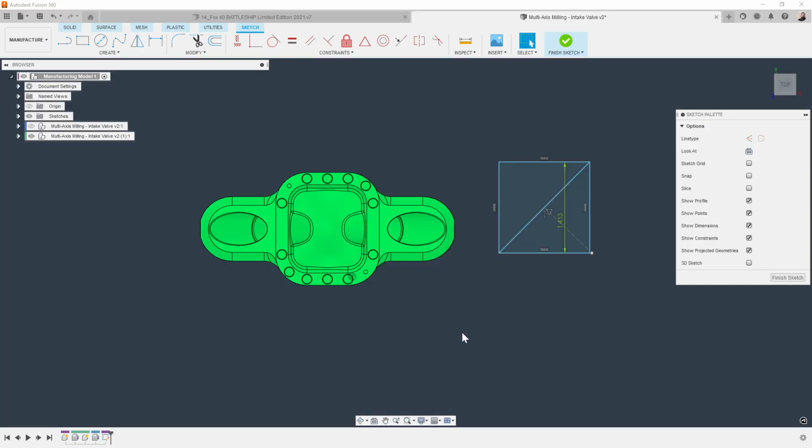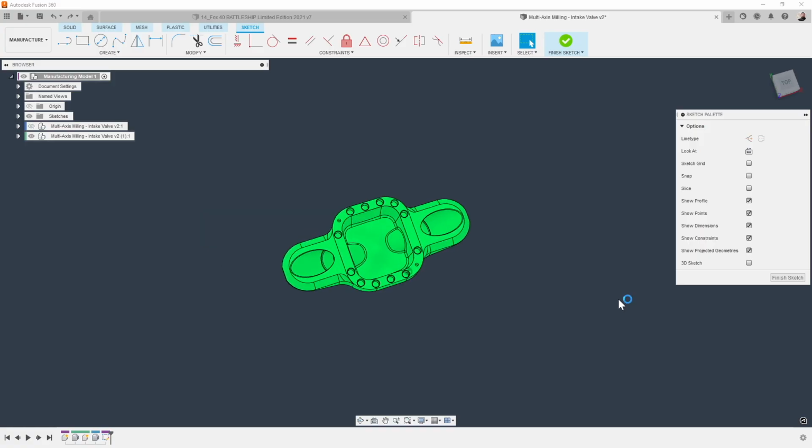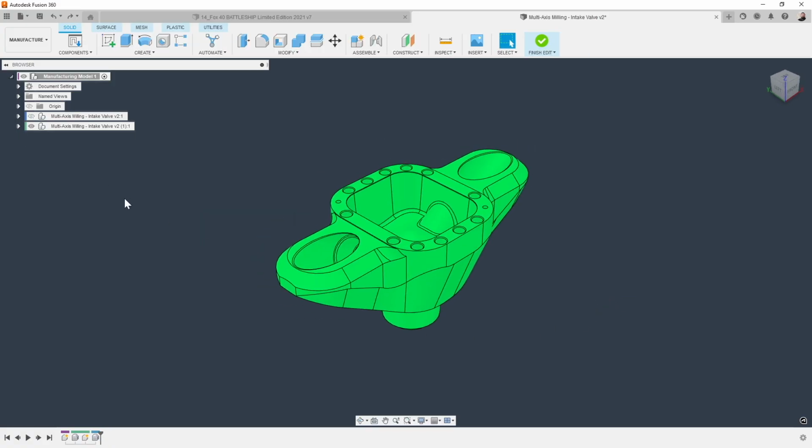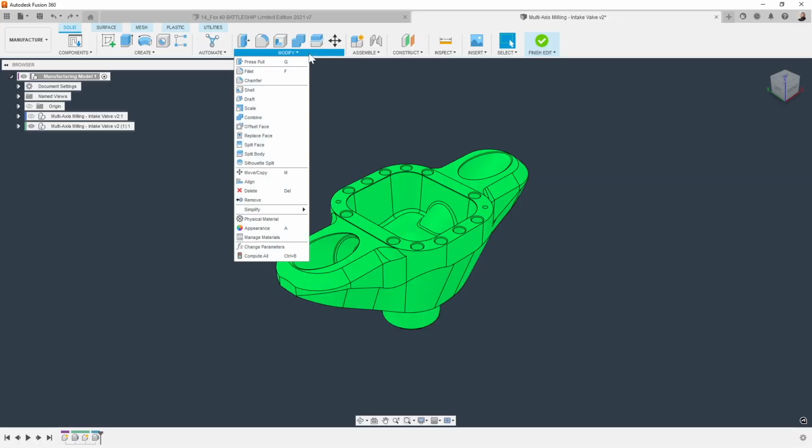But I am liking it. It's kind of easy on the eyes, right? Especially if you're staring at Fusion all day. I love the green visual tip. That's a really good idea for making sure you don't get confused about which model you're in. Yeah, it's just something I always did because you'll have staged models or process models that you'll do sometimes for a casting or something like that, or maybe something has to get roughed out and sent out and come back. I usually just save that model as a different color.